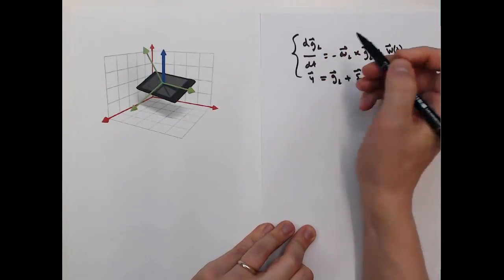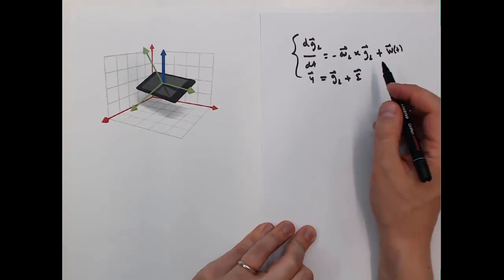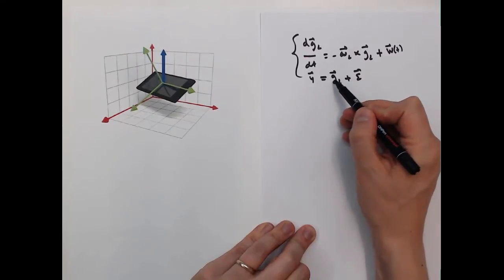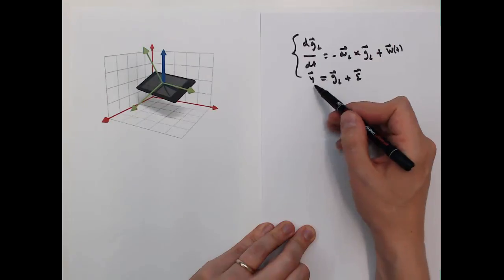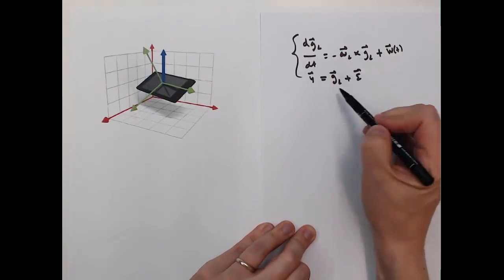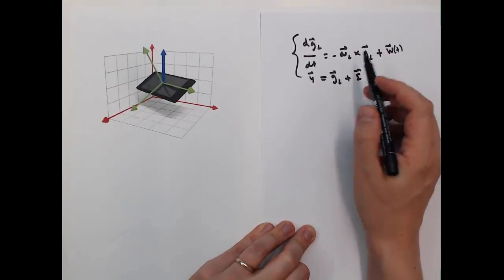And now there exists a class of estimation algorithms called Kalman filters that can be used to track or estimate the G trajectory from observations of Y in the mean squared sense. So you can use a Kalman filter together with this kind of dynamic model to track the orientation of the mobile phone.